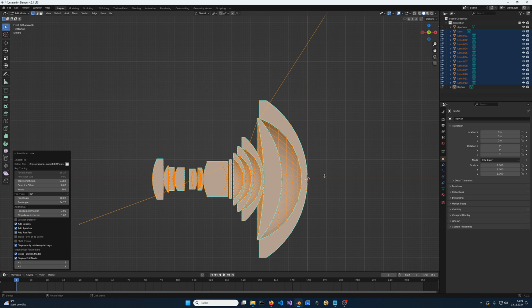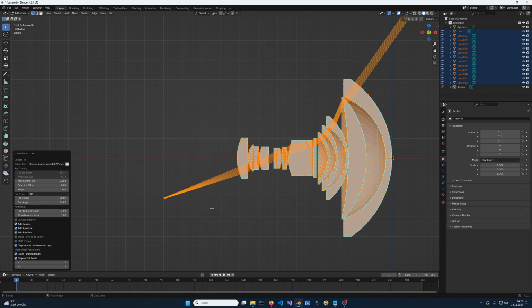For a non-fisheye lens, as I said this one is, we can then assume so-called f-tan-theta projection, which means that the distance of the focus spot, if I add a few more rays to really highlight the focus spot, so the distance of the focus spot laterally from the optical axis, is the product of the focal length times the tangent of the image angle. Together with the effective focal length of 50.3 millimeters in this case that OptiCore calculates here, you can actually enter this as an equation into the Blender UI, which is a really nice feature.